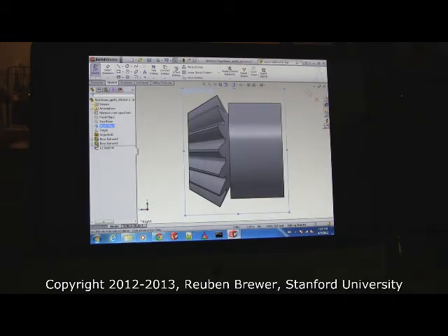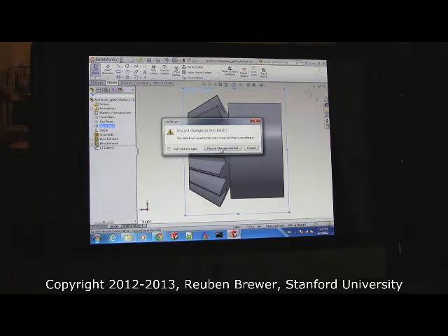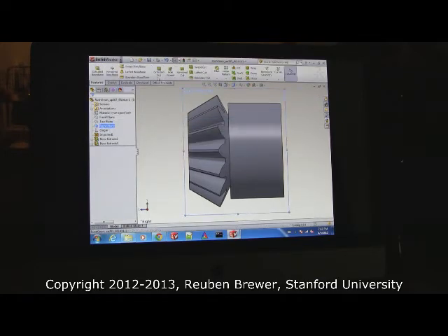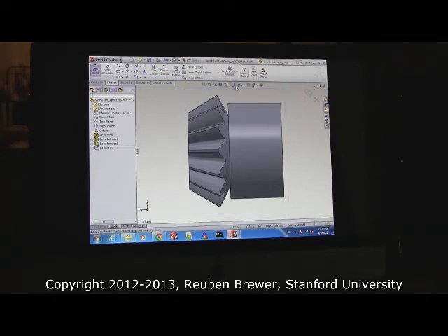And I'm going to wait for everybody to get here. How do you select right plane? Just click on it in the left-hand side, where it lists right plane. No, Extrude Cut. Here, I'll do it again. Right plane, Extrude Cut. Okay, everybody here? All right, now turn to wireframe so we can see through the part.